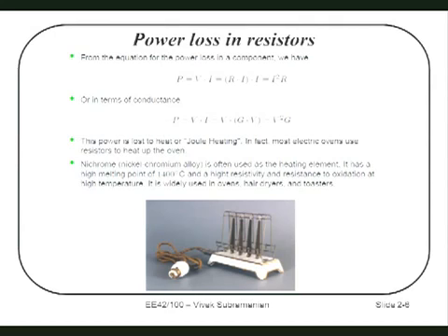Why did we use tungsten? Two reasons. One, tungsten, it turns out, for the kinds of voltages we use, has about the right resistance to get hot enough. And two, tungsten has really good high temperature capability. It can handle high temperatures really well without evaporating and burning out very quickly. That's why. But the first light bulbs were not tungsten filament light bulbs. Anybody know what they were? Carbon filament light bulbs. It was really interesting.